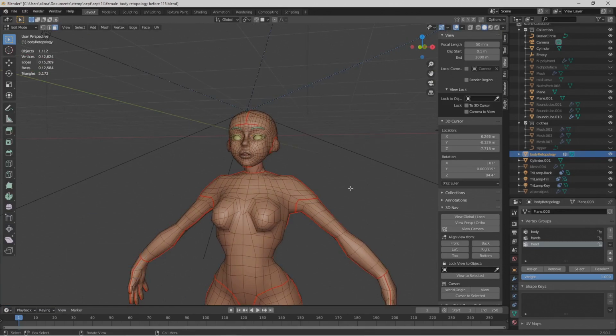Right now, the polygon count is 5,172 triangles. If you need low poly geometry, I would advise you not do this next step. I want there to be more detail to the mesh. So I'm going to add a subdivision surface. It's going to bring this up to probably higher than 20,000 polygons. Generally, when I'm working on a character, I'm good with 30,000 polygons. So I'm just letting you know if you want to keep your character fairly low, don't do this next step.